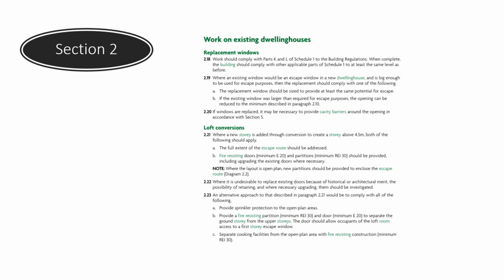So, coming to your point about loft conversions. The first section at the top there talks about replacement windows. What it says basically is that if you're replacing the window that's being utilised for means of escape, then you shouldn't be reducing the opening area. So this is something that competent person schemes, FENSA for example, should be fully aware of if they're replacing windows, and those are the only works that are taking place.